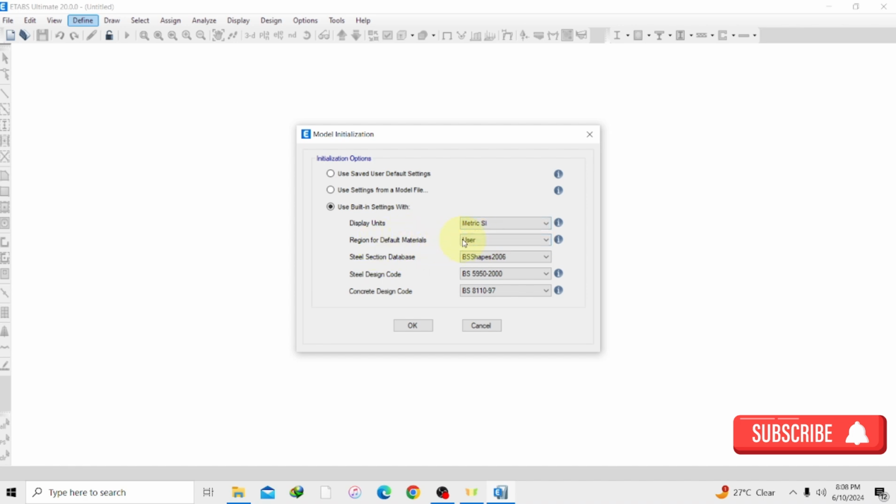We also have region for default materials. This one is based on the country whose code you're using for your design. We have China, we have Europe, India, a whole lot. But in case you don't have your country code here, you have to select user. Since I'm using a BS code and Ghana is not really in these options and Britain is also not here, I'll just have to select user.